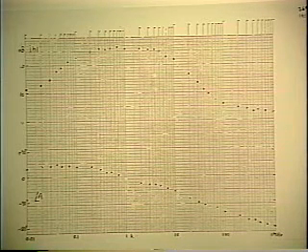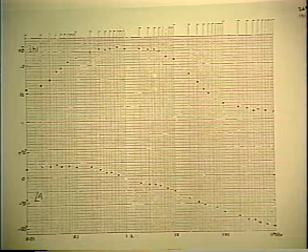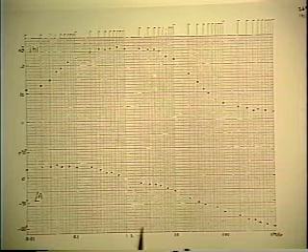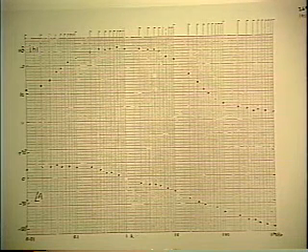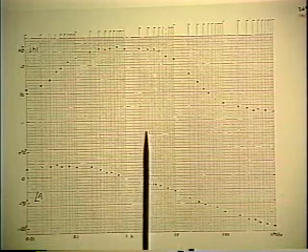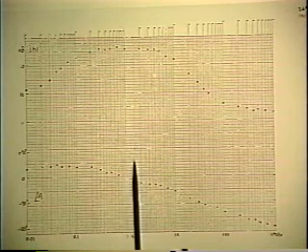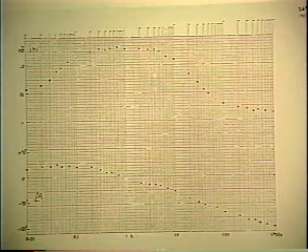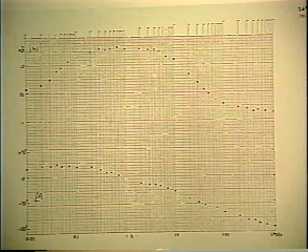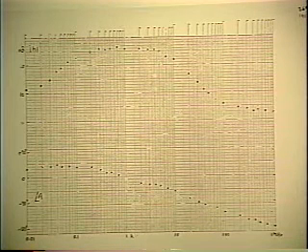And the first thing we need to do is find the equivalent salient features, that is the flat gains and the corner frequencies that these points correspond to. So we want to do a geometric construction of the asymptotes that best fit the data points. The other way around from what you do in analysis, which is given the formulas, you can draw the graphs.